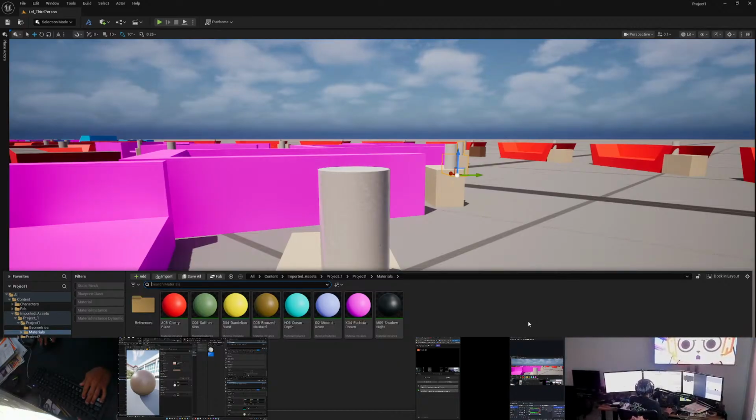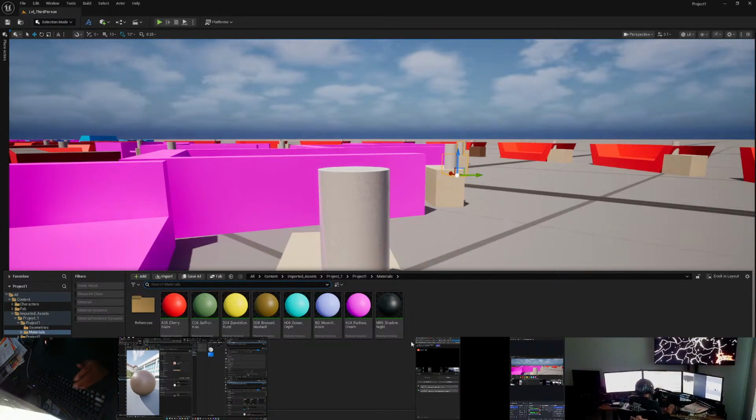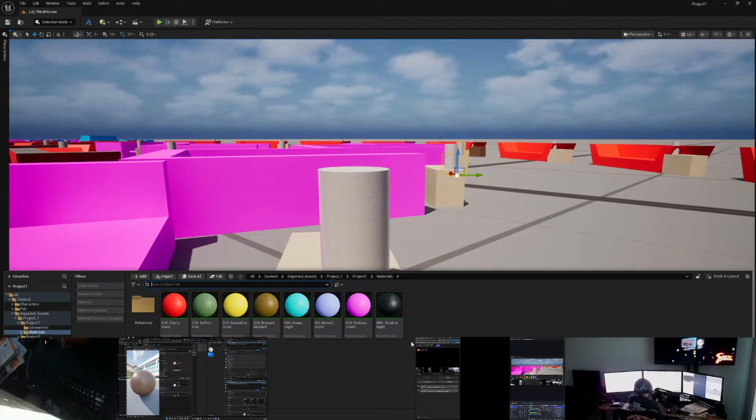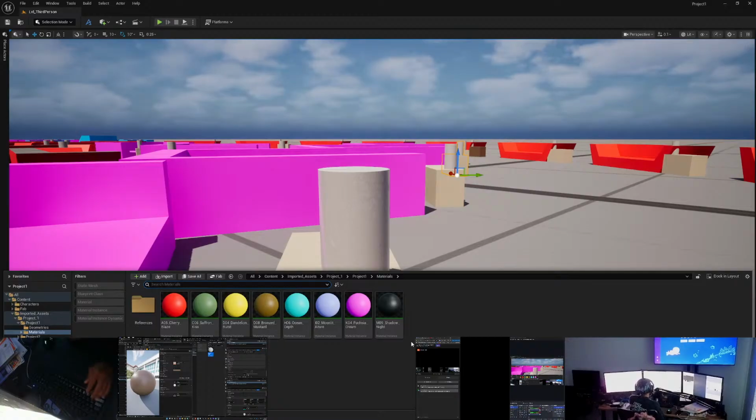What I could do is move those materials over into my materials folder. But since they're fab materials, I don't mind keeping them there for this particular project. But if I were wanting to package this project and share or sell it, I would want to bring all of my materials into one material folder, have them all named accordingly, and then have them share a master wherever possible.